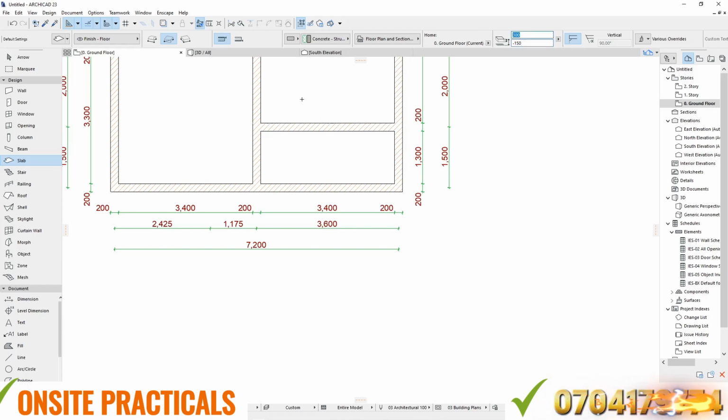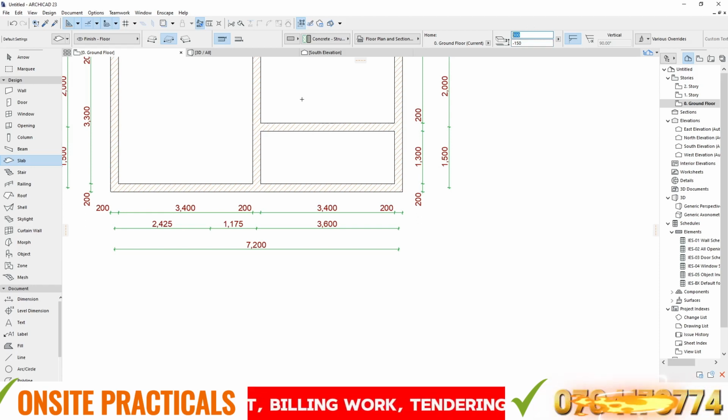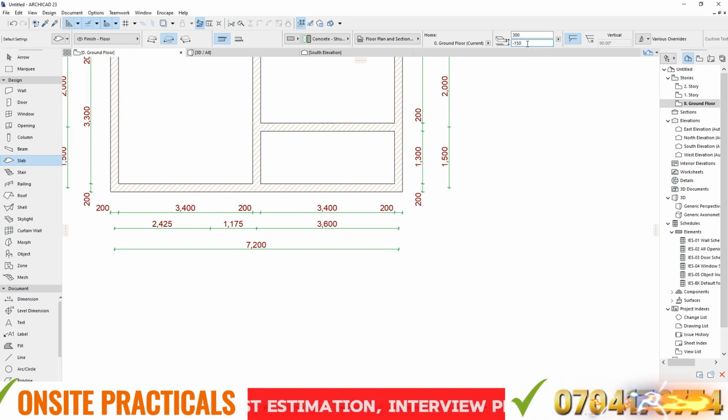Remember, guys, that when you're building, you're trying to compare different levels from a certain, what exactly we call the benchmark, right? So in that case, this was a 450. Now we're going to have that height be 300, and then I'm going to go down by 150, so that I have a step of 150. Now, if I go down here by 100, it means now the step will be 100.